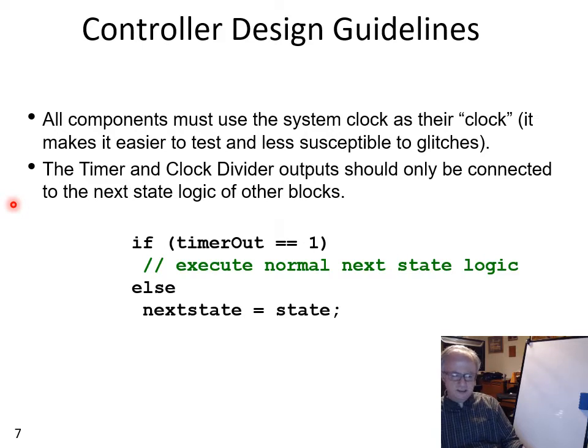It makes timing analysis of your design much more difficult, and it makes your design very susceptible to variations in delays of different logic gates that lead to somewhat unpredictable arrival times for clocks.